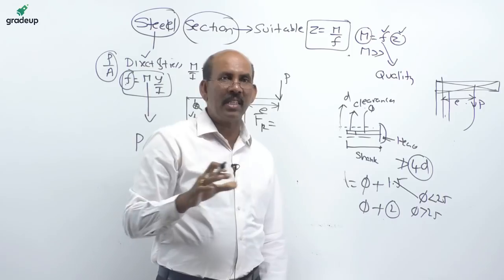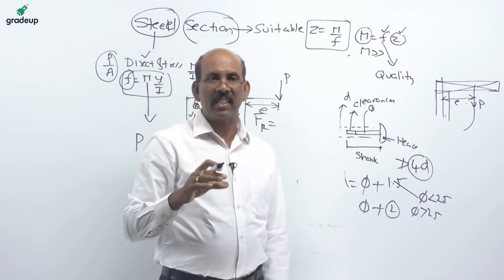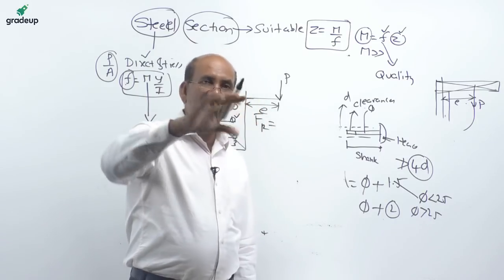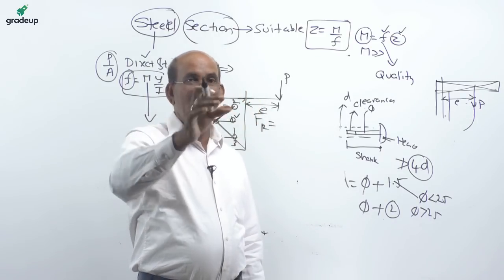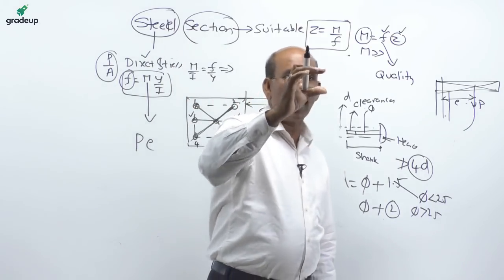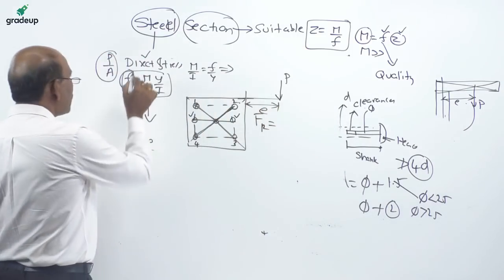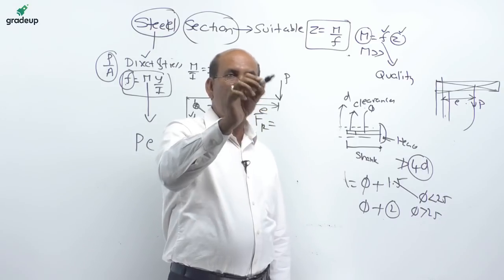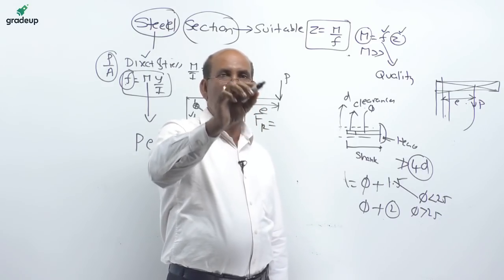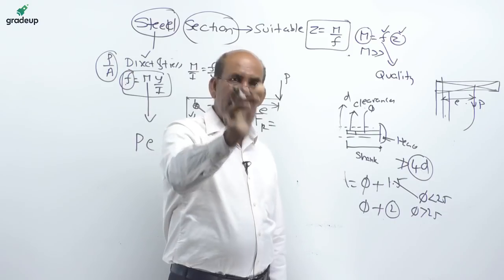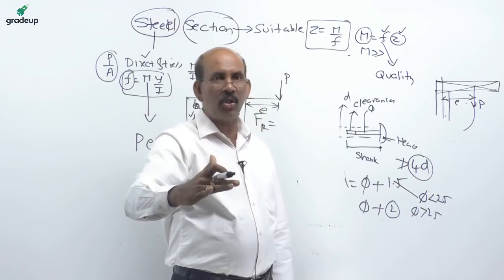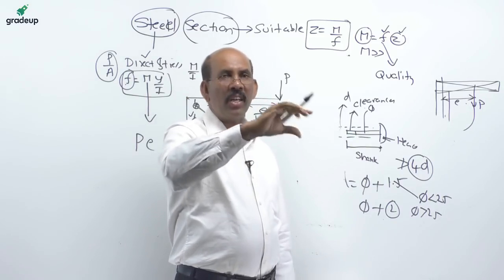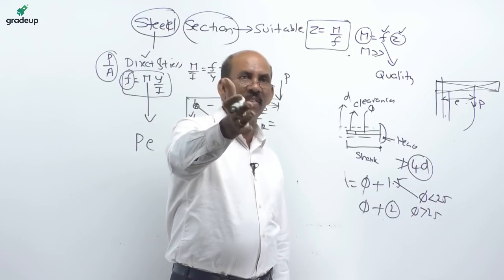In-plane eccentricity causes twisting and direct stress. The twisting is associated with the shear, which is due to the shear force. Direct stress is always there with reference to the direct load, and bending causes bending moment; it is not the twisting, twisting is related with the shear.